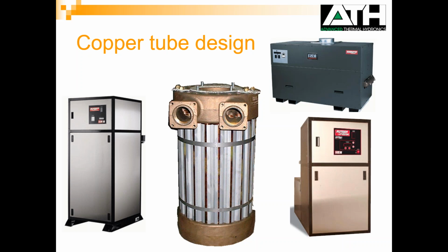Really a very compact type boiler, very widely used, especially here in Southern California, also known for having a lower first cost, especially compared to some of the stainless steel type of products. Then you have a horizontal copper fin, which has typically stage firing, a vertical copper fin, which has typically been modulating, and then you have a vertical high efficiency condensing unit down there on the right.